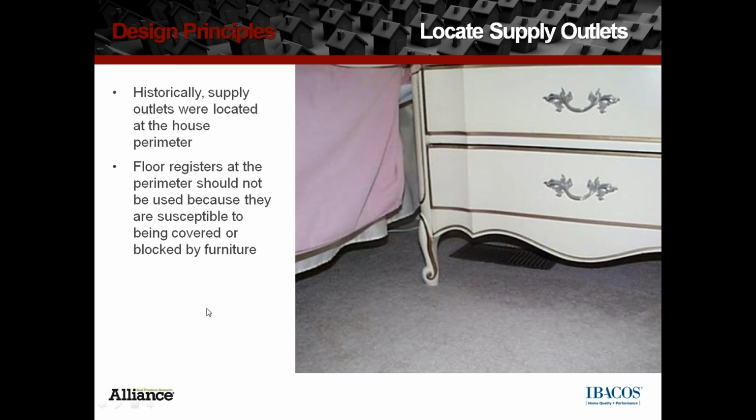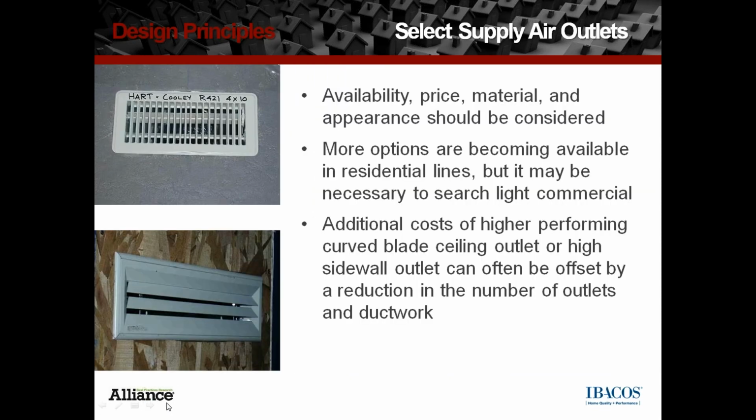One more word on placement of diffusers and why maybe a floor diffuser is not the best place. You can't predict where homeowners are going to put furniture or where the dog is going to lay down to take a nap. Floor registers are easily covered up, blocked by furniture placement, which will definitely impact the performance of the system.